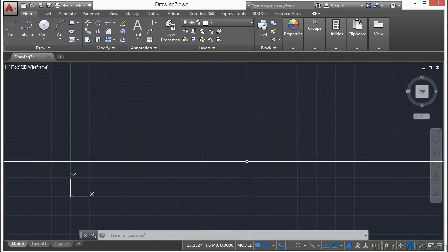An example of that might be a surveyor needing to work with a coordinate system that is offset, possibly rotated, from a specific point of commencement or some other land-based marker. Now, this will allow the surveyor to work very easily in a coordinate system that is relative to the property boundary, but yet still relative to its referenced real-world coordinates. Another reason to rotate your UCS is to draw in an isometric or rotated plane.